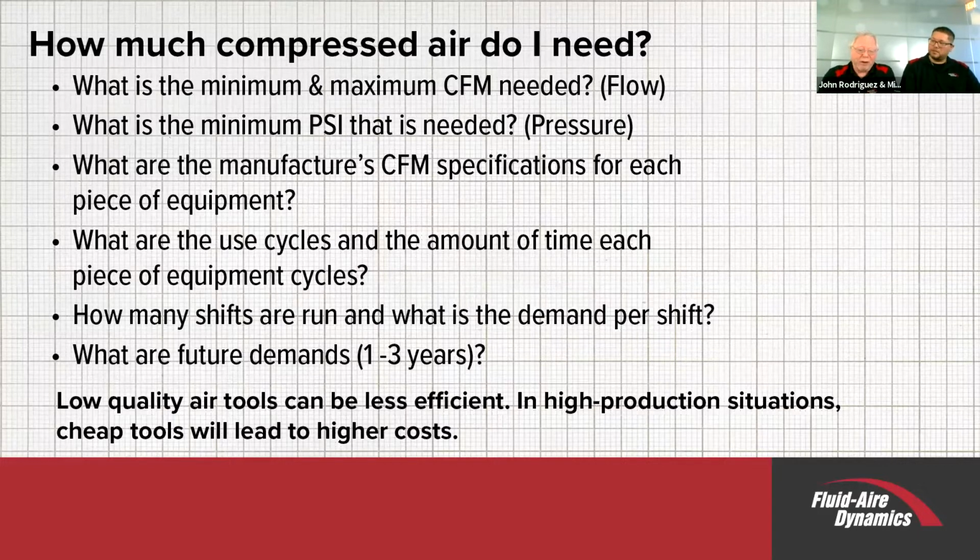Also, watch the type of air tools you use, as air tool manufacturers will come up with a CFM requirement. Matter of fact, some of the less expensive tools use more air in their specifications. You could have a $100 air tool, let's say a grinder, that would use 10 CFM. If you were to buy the same grinder in a higher quality tool, let's say one that sells for $300 or $400, that might use 5 CFM.